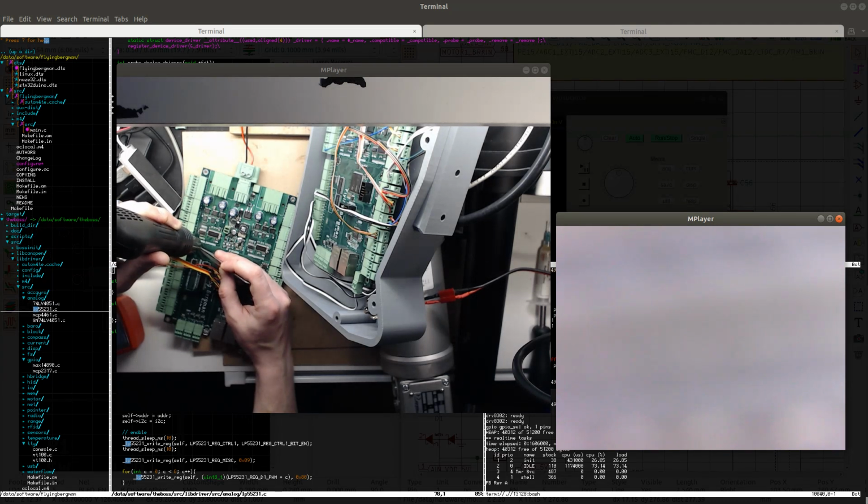Kind of seems like the solder mask that's on the ground pad is lifting the package a little bit from the PCB, so some of the pins don't actually make very good contact.